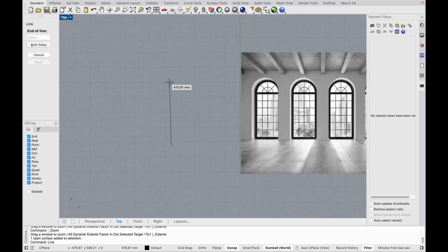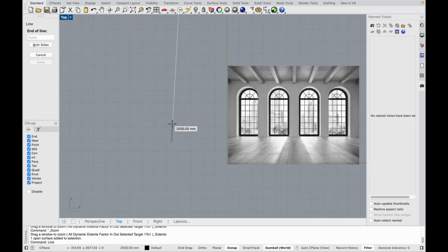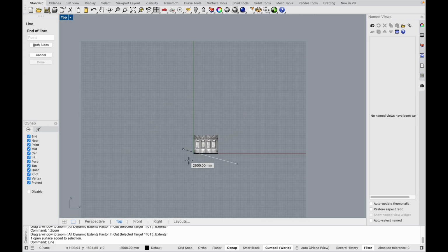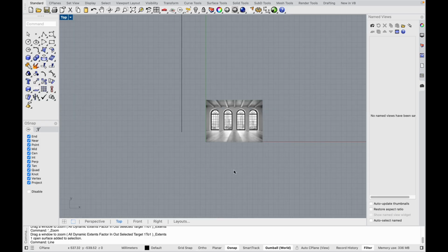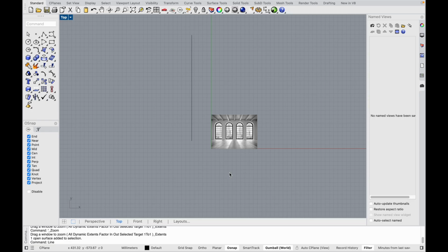Well, let's make a line about 2 meters and a half. Press space. So I type in 2 meters and a half. Press space to confirm, and now I have this distance on my cursor, and I hold Shift to snap to vertical direction, and then press the left mouse button.